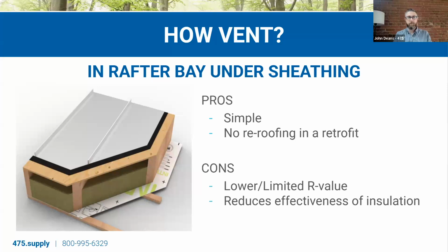We might not have the headroom to furr those rafters down, or maybe we've got to thicken them. So, that's one of the aspects. And we're passing air across the top of our insulation. And with fibrous insulation, we know if things aren't packed in there totally tight and all perfect, we can get wind washing. We can get condensation and moisture building up in a process there, which from a durability standpoint might not be too much of a problem, but it's going to reduce the effectiveness of our insulation.